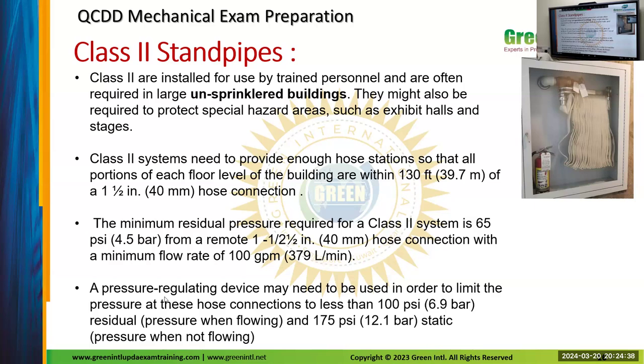There are two separate lines, with a separate valve. That is for high-rise buildings. In some areas, both connections will be given to the standpipe systems. Even the sprinkler lines are taken from this standpipe system, and a separate connection for the hose reel is given. Yes, it will be distributed. In the zone control valve, there will be NRV, PRV, and everything.